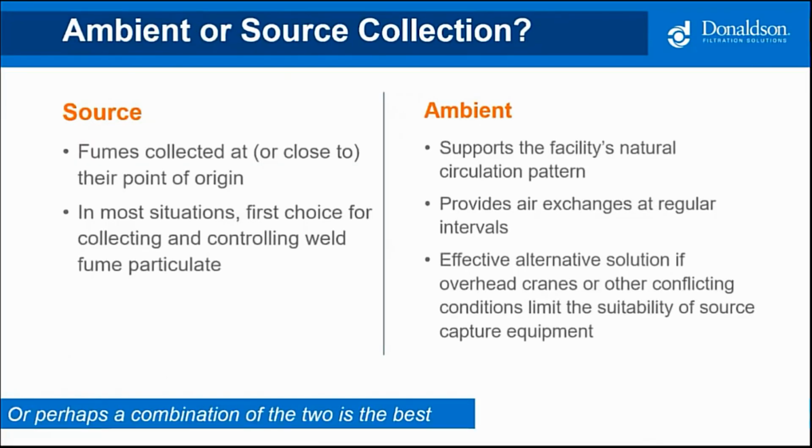So we're going to address two areas that we can design for in weld fume. The first being source capture, and that's pretty self-explanatory. We're going to try to capture the weld fume at the source. When we capture at the source, typically that takes it away from the breathing zone. The two best filters in a plant is the lungs of the individual. So if we can attract this weld fume away from that breathing zone and then capture, filter, and exhaust either to the atmosphere, clean air, or back into the plant, we have done a good job.